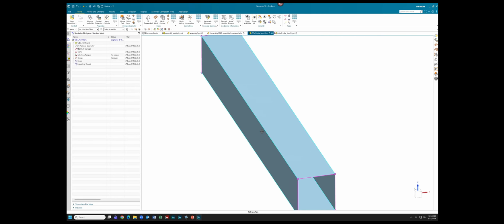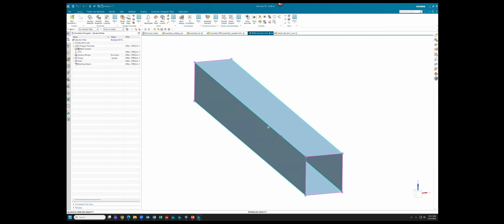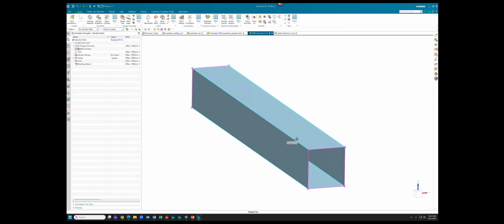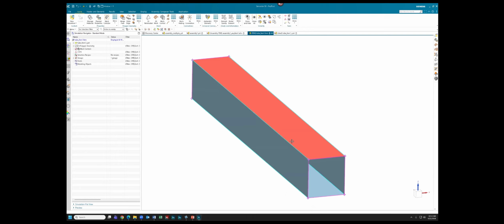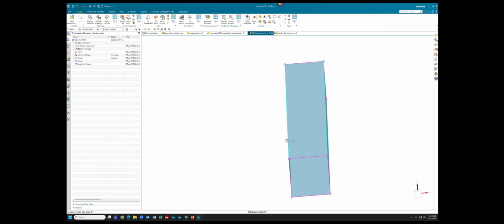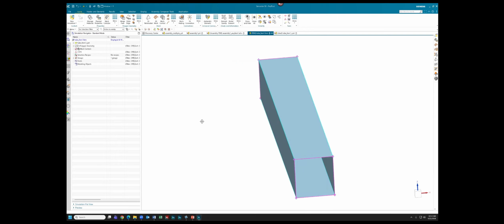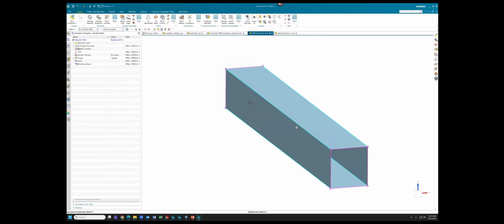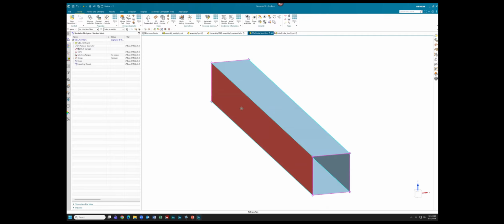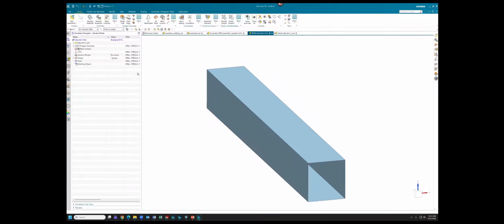And then we can visually confirm with our geometry that our stitch edge operation was in fact defined correctly, and we're getting stitch edges across our sheet bodies where we expect. That's something, again, that I appreciate about SimCenter, is having these types of visualization feedback to be able to confirm that the software is in fact doing what you expect.